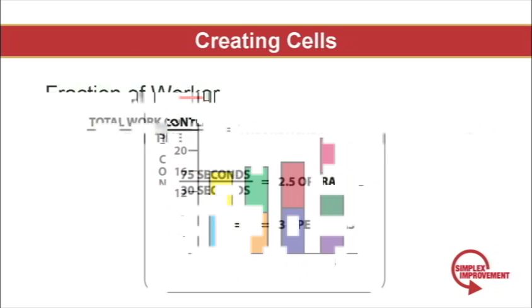If the fraction is less than 0.3 of a person, then round down. You'll be amazed at how the remaining workers quickly absorb work and still meet takt time. If the fraction is between 0.3 and 0.5, then round down and try to Kaizen that area for the next 1 or 2 weeks. If they still can't meet takt, then add the person back. As a side note, I've never had to add the person back after this Kaizen period. Now, if you're stuck with a fraction that's 0.5 or greater, then round up.